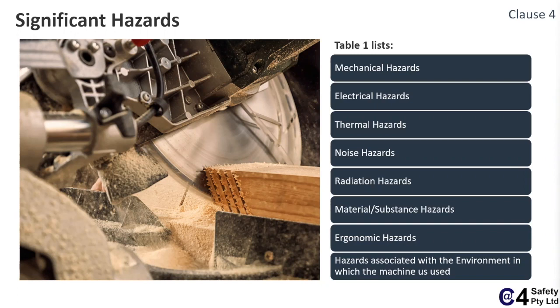Think of machinery as only having mechanical hazards, but of course all that list there are all typical machine hazards, all of these things here. And the material itself, there may be dust or gaseous emissions, which are hazardous. These are machine hazards. Of course, these are all listed in part 1201, which is ISO 12100. The list is very comprehensive there, but this refers to the specific hazards related to the woodworking machinery. And as you go through the very specific machines that fall under this overall standard, they'll be even more specific to that very machine.